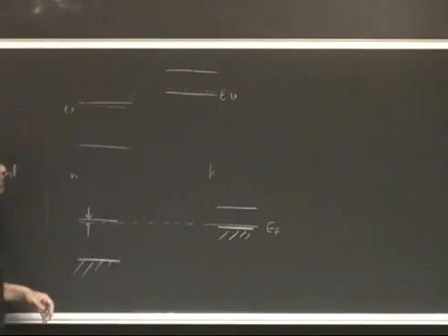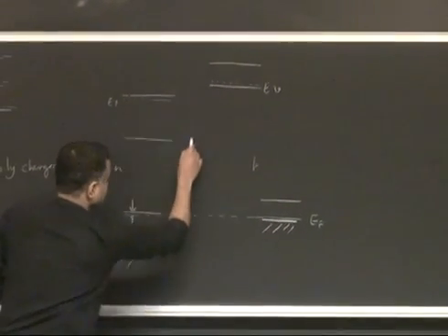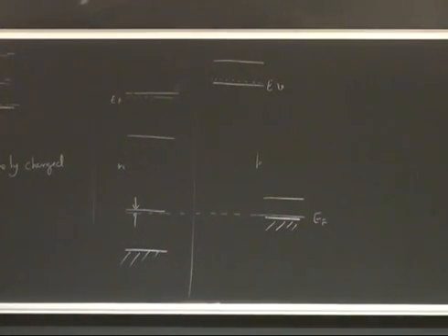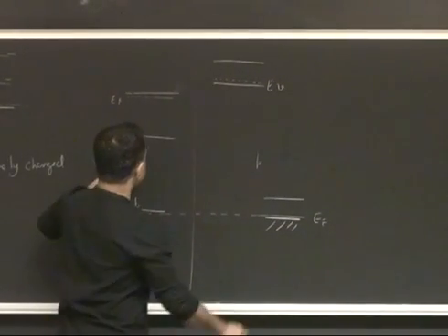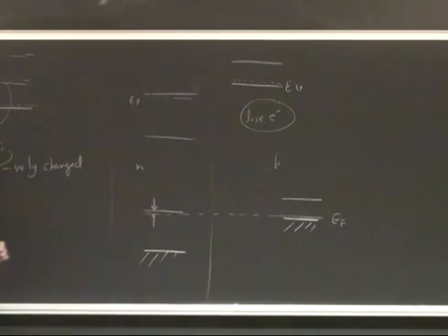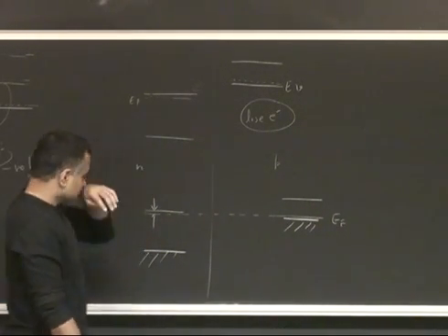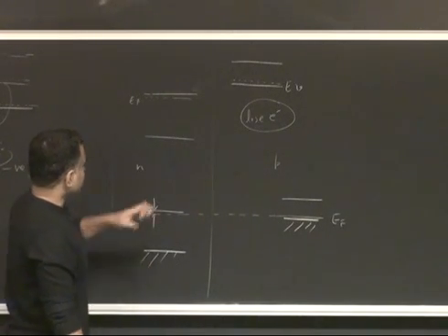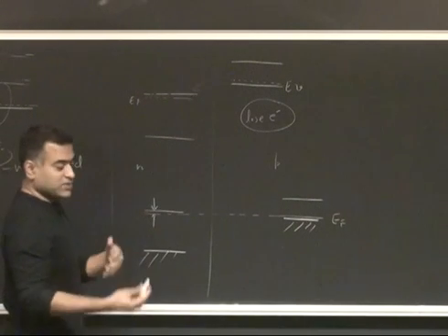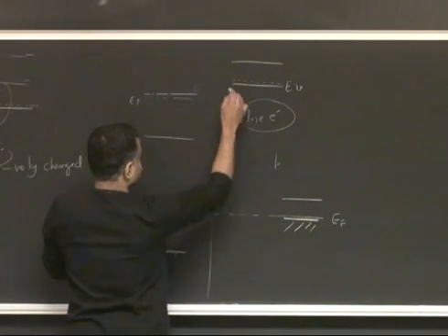And now you can see the way it's going to actually form the heterojunction is somewhat non-trivial and quite interesting. So the p-type layer is going to lose electrons, right? But you realize it doesn't have many electrons to start with, right? So how is it going to actually do that? And the n-type layer is going to gain electrons, and it has a lot to start with already, right? So let me just sketch out how it's going to look in the end.